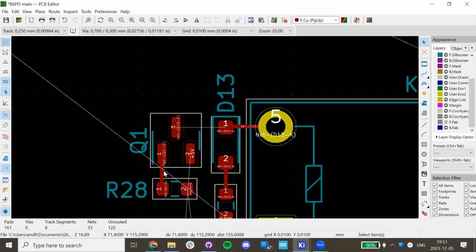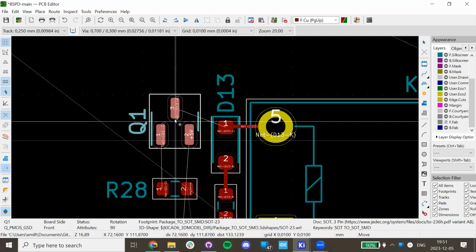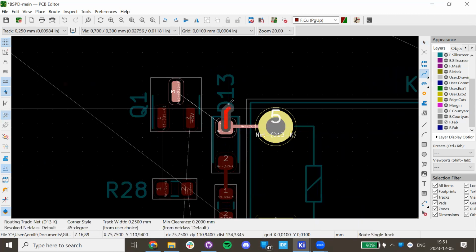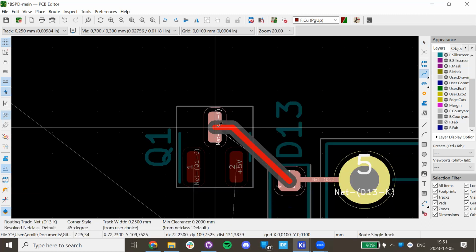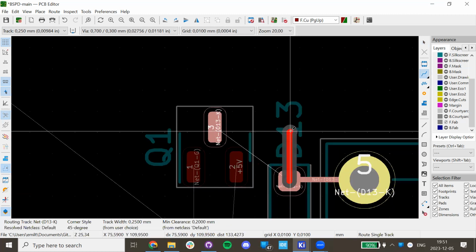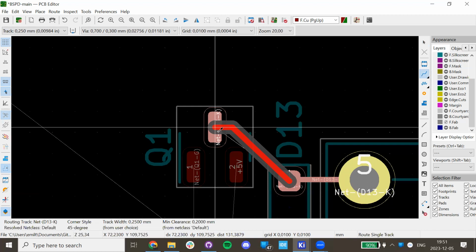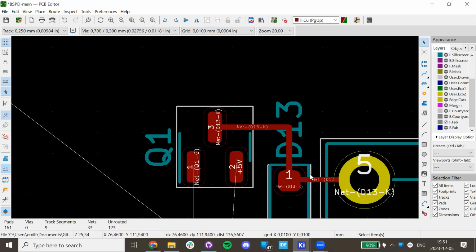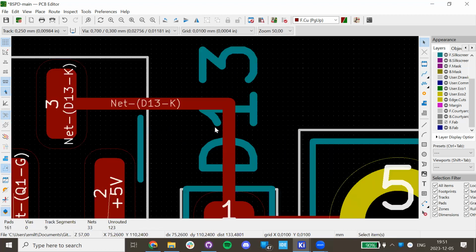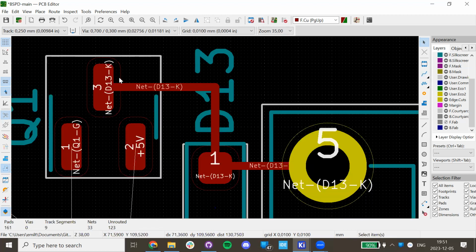Now it's a bit unintuitive, so I will do this. If you have a trace coming up like this, and you want to connect it here, what you should do is always keep 45-degree angles. Or not 45, but keep it non-90 degrees. So if I go like this and I do this, this is bad. This is kind of unintuitive because it looks nice.